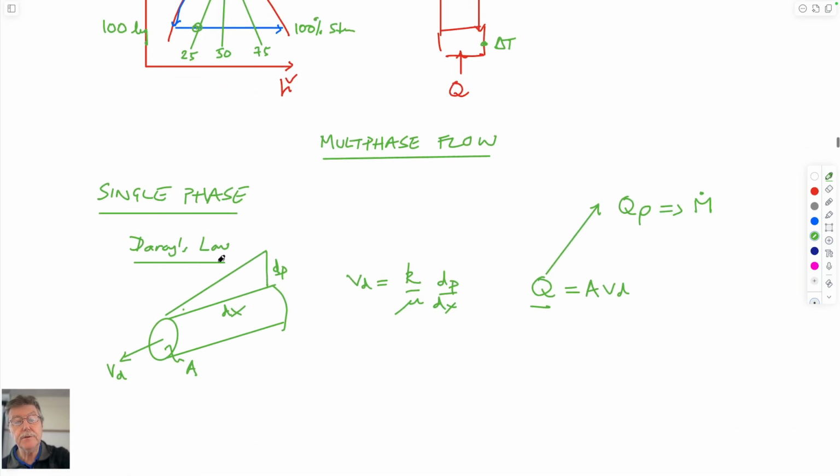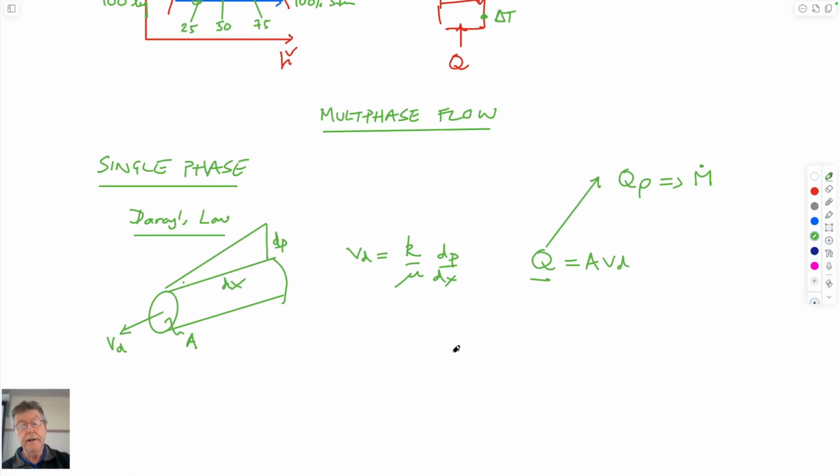And so if that's the case, we have to be able to quantify how the fluids pass through our reservoir. And to do that, we merely use a construct whereby you imagine being able to divide the flow system into liquid and gas. Typically, if it's water, it's a wetting fluid, and if it's gas, then it's a non-wetting fluid.